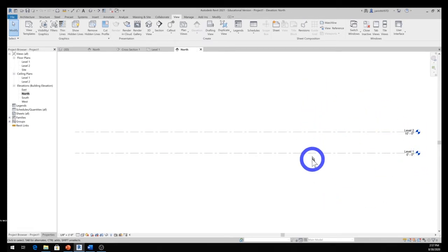We're going to change these because when we design a house, we're going to have different levels. And the levels are really a good reference point we need to use. Normally, in a house design, architects use elevation 0 on the first floor, and everything is referenced based on that. However, in civil engineering or surveying and other disciplines, you might see the elevation based on sea level. So your elevation could be 100 above sea level, or whatever it is, depending on the location.